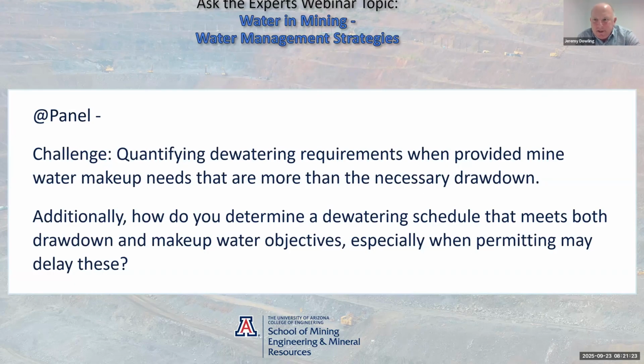So you either need somewhere you can store it, which could be another facility on site if it's an older site and a legacy site that may have some older mine workings or open pit areas or a tailings facility with some freeboard. You could try and find some areas in the mine where you can store some water and pump it around basically inside the mine without discharging it.